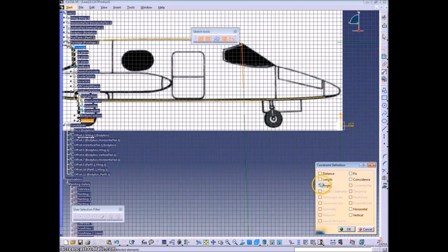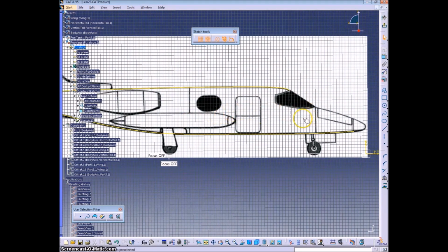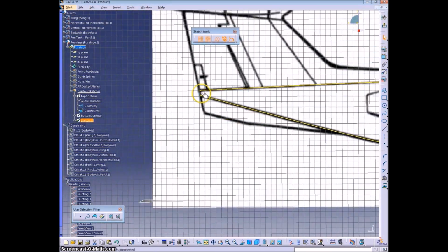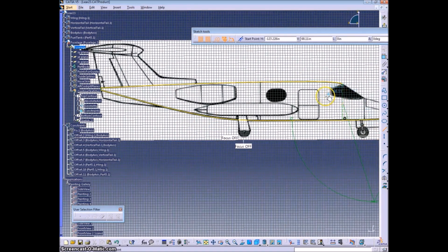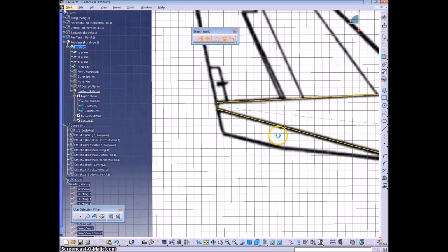In this case it wasn't giving me parallelism, so I'll set an angle to 180. And we'll put a point or constrain the line endpoints to the sketches that we had before. And reset the angle measurement or constraint there. It's given problems. Okay, then we'll add a spline. I don't know, 4 or 5 points from here back.